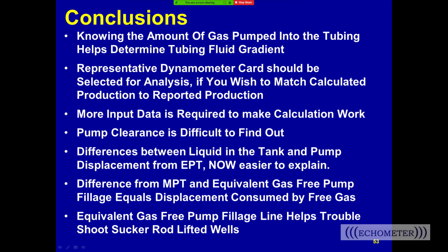Often, if you're using the TAM software, you haven't clicked the annotation button and turned on the valve open close points, and sometimes the program's not picking the points right. So the first thing you need to make sure is to select the valve open and close points, and then look at the calculated pump discharge pressure and the calculated pump intake pressure based on the height of the pump card. Those are fairly important in this whole calculation.